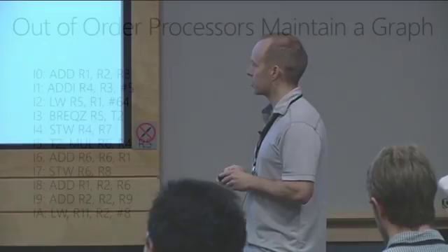And so what you do with that bloating is you're actually conveying a lot more information from the compiler that allows you to save energy at runtime. An out-of-order core will discover all of these relationships between instructions dynamically using expensive hardware. We're actually doing that analysis. Well, the compiler already knows that, but we're conveying it through the ISA to the hardware. And the cost is an increased binary size. The benefits are that you can run efficiently with much, much less energy. And so I'll show you how we tackle those three things.